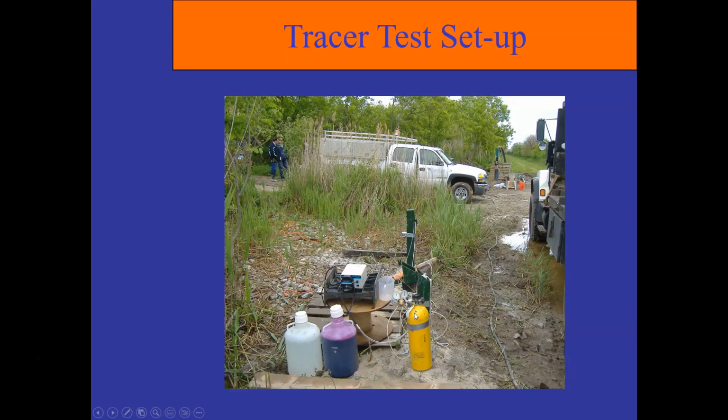We actually had, because this well is so close to the pumping well, a packer set up in this well above the well screen. So this inlet tube carries the rhodamine WT, and this jug here has water in it to help flush the rhodamine out of the well screen. So you pump this rhodamine in first, followed by the water to just make sure it gets out into the formation. But we had a packer set up there to make this well more responsive to drawdown.